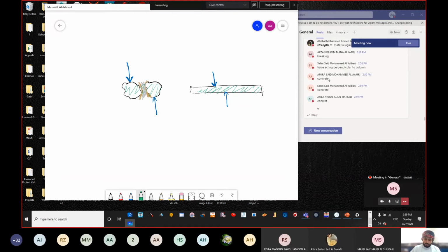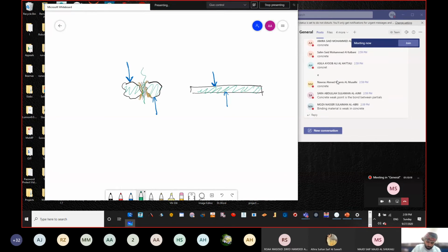Okay, you will see that steel is a coherent material, where no gaps are appearing. It means that it's hard for you to cut it. It's easy to cut wherever there is a weak point. And you will see that in concrete, the weaker point is available at the joint. If you try to apply a large shear force, concrete is not going to be strong because of the binding area. While when we talk about steel, it's good because we don't have weak points like whatever we have in the concrete.